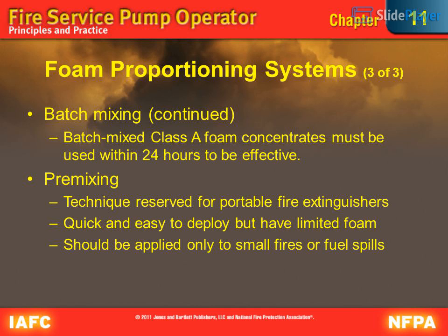Foam proportioning systems, 3 of 3. Batch mixing, continued. Batch mixed Class A foam concentrates must be used within 24 hours to be effective. Pre-mixing. Technique reserved for portable fire extinguishers. Quick and easy to deploy but have limited foam. Should be applied only to small fires or fuel spills.